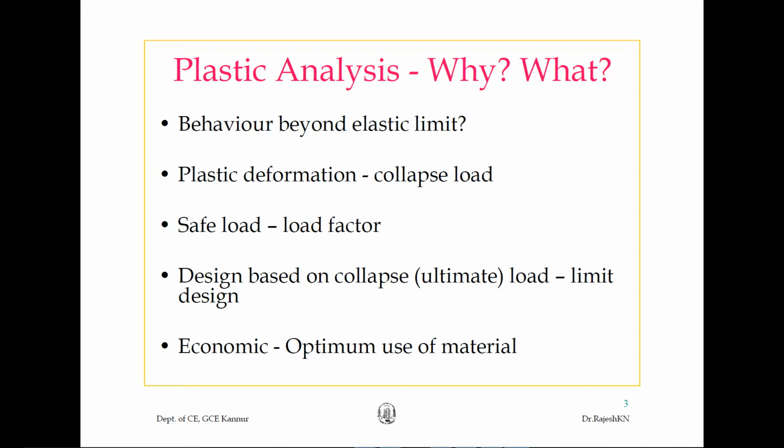And what is the elastic limit? It is the limit of a material like steel, or any kind of material, it could be cork. The elastic limit ends at the point where stress is no longer proportional to strain. What I'm trying to say is that when stress is proportional to strain, that is known as the elastic limit. After that, the material yields and the plastic nature of the material starts.